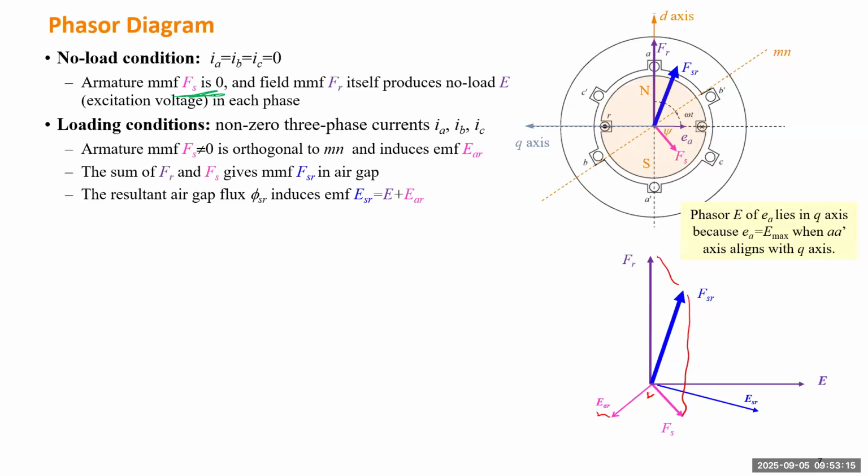So far we have three F's, right? We start from FR. This one is always there, even when the system has no load, because as long as you have field winding current, it has this value. So it induces a voltage even with no load, which is like having a DC battery. Even if you don't connect the battery to a circuit, if you measure the voltage on both terminals, you still have a reading. And this voltage is induced by the stator winding only, so this is smaller.